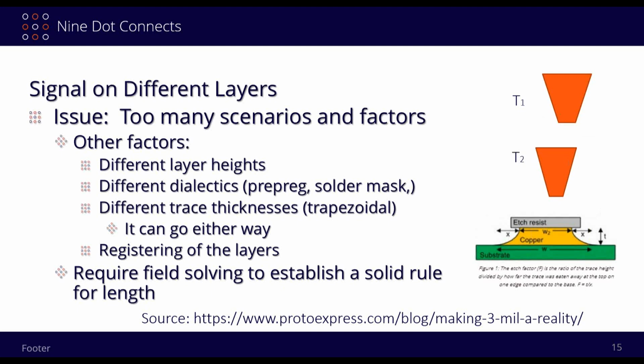There's one example I was given, and I forgot the name of the material. Someone wanted to use 8 layers of it because its dielectric constant was phenomenally low. They said, this is great stuff. So they went off and did this layer stack on their own. Then they went to the fabricator and said, make this for us. And they quickly found out that they couldn't make it because this material is only good for maybe 4 layers at most, and the registrations wouldn't work. So just bear in mind that even with known processes like FR4, this stuff could travel away from each other.